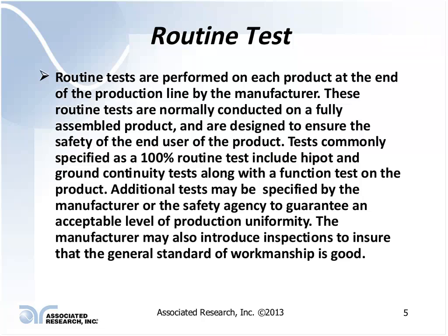Why do they do these tests? These tests are done because they are essentially looking for defects in workmanship that could create a potential shock hazard. Could be possibly some reverse wiring, could be damaged insulation where maybe somebody has pinched wires, component spacing where you don't have sufficient clearance because of the way a component was assembled within the product itself.